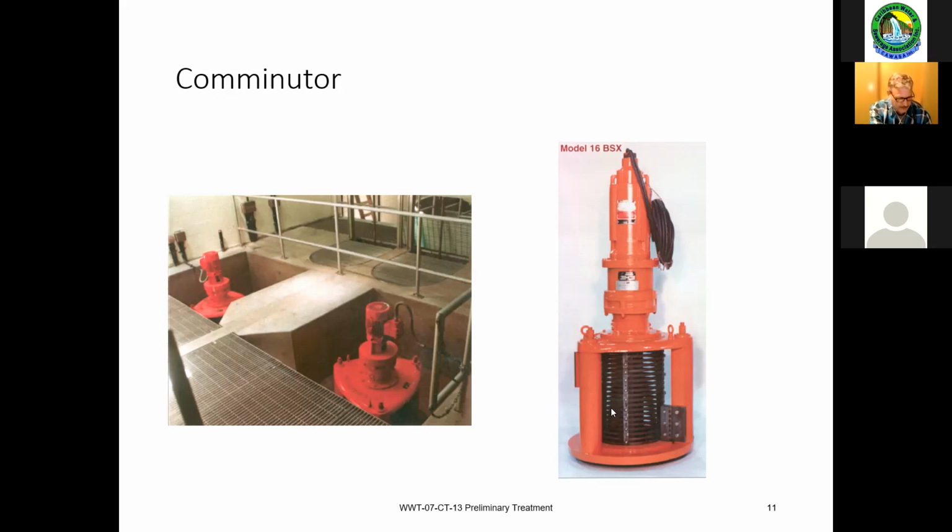There is a really good application for this type of equipment or grinder type pumps in a collection system. In a collection system, they're making the rags or pieces smaller so they move through the system. Like in our scenario, we have a 10 millimeter plate screen at the plant, so we have a lot of grinder pumps in our collection system.